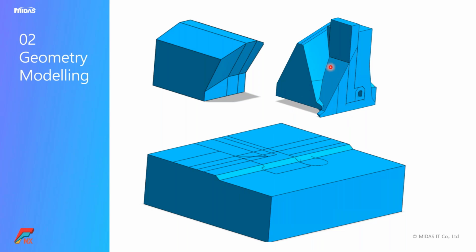And then we have a dam abutment, basically a wing wall, shear wall. It is made of M20 grade concrete, which has 20 Newton per mm square of strength. That's the compressive strength. And this is the backfill. If you notice, we are not applying the backfill as a pressure onto the abutment, but rather we are modeling the entire backfill. So this is the backfill with soil properties, and we are not applying it as a load, but actually modeling it as a continuum.